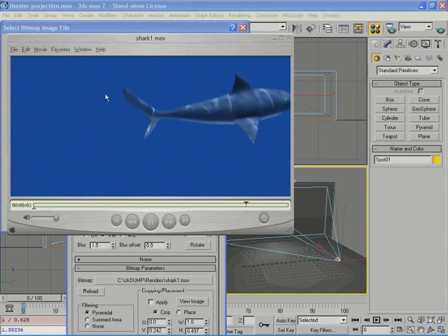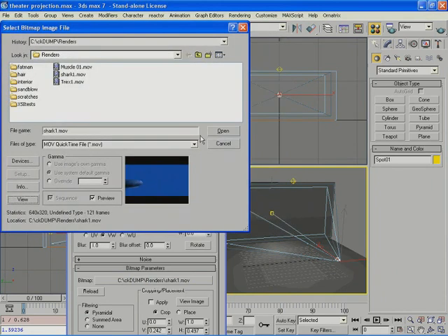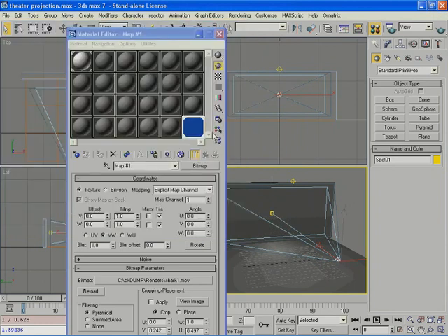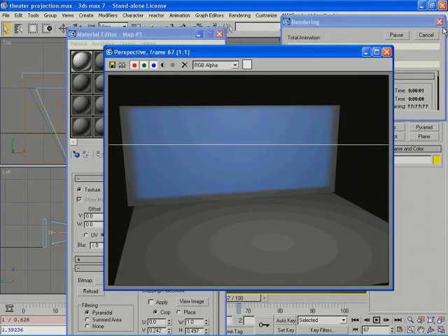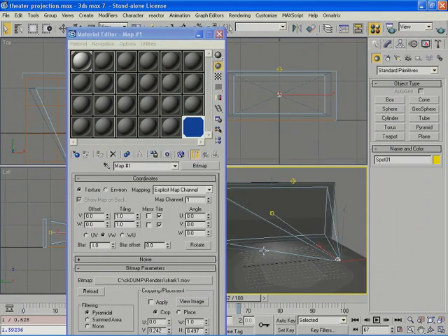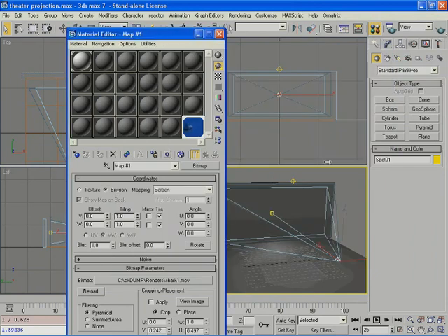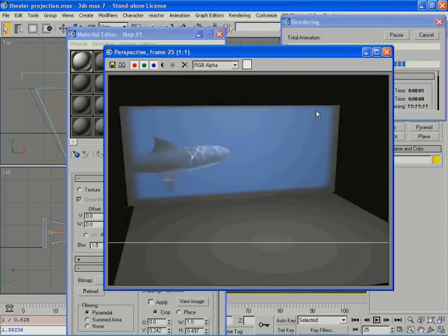So I'm going to open that, and this is what I have. In case I render, I'm going to get just the normal rendering here. Okay, so here I need to set the environment type to screen, because so far it was set as a texture, and it should be environment and screen so that you see it properly projected on your screen.